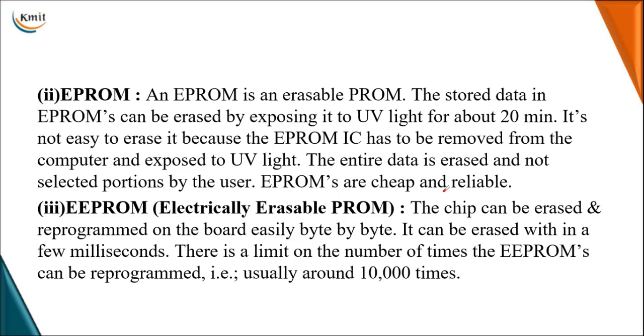But this process of erasing will take more time. Along with that, you have to remove your chip from its processor, and then you have to expose that to UV light. You have to use a window, and through that window we transfer the UV light. So the entire data will be erased completely, not a portion selected by the user. So this is the only disadvantage. But these are cost effective as well as very reliable, so we can prefer EPROM devices if you are looking for erasing or reprogramming your read-only memory devices.